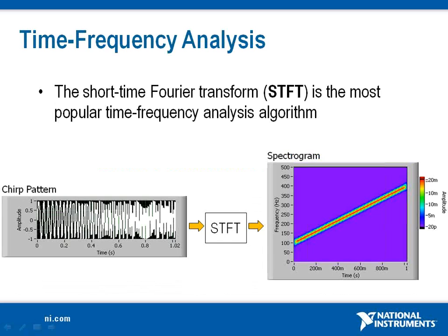The time frequency analysis results are usually given in a spectrogram. A spectrogram shows how the energy of a signal is distributed in the time frequency domain. A spectrogram is an intensity graph with two independent variables, time and frequency. The x-axis is time and the y-axis is frequency. The color intensity shows the power of the signal at the corresponding time and frequency.